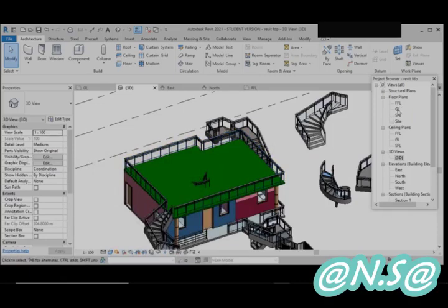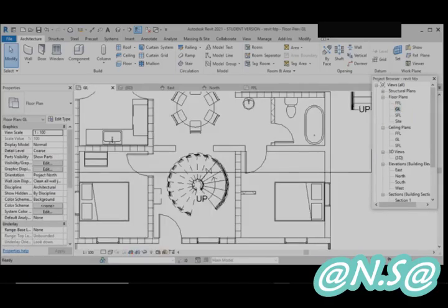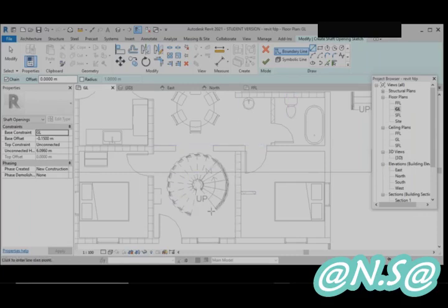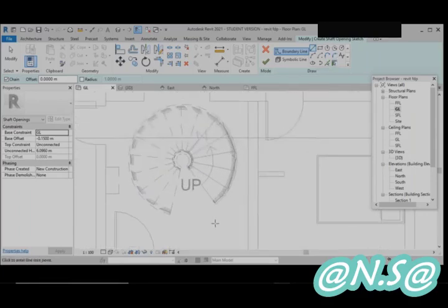So for that purpose, simply open the ground level. Okay. So listen carefully. This is a very important topic, and it is also a little bit confusing. So, creating the opening in the roof: a vertical opening, nothing but a shaft opening here. So click on shaft openings, and you can find these draw tools. With these draw tools, we need to draw the opening.